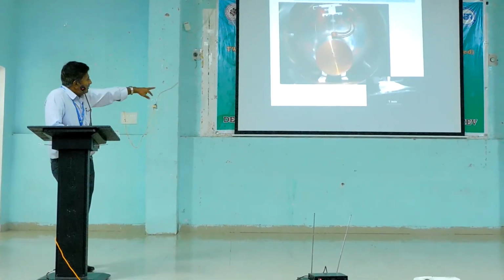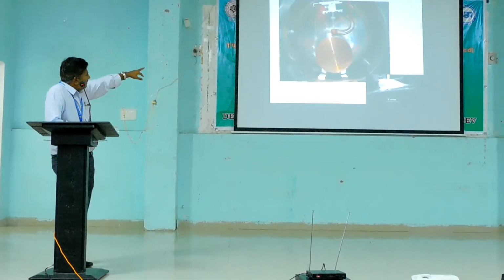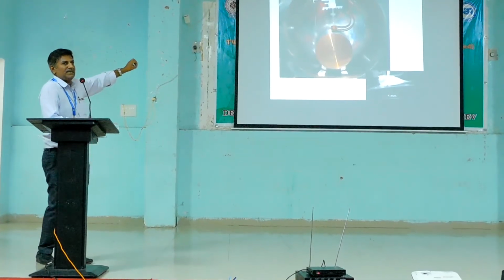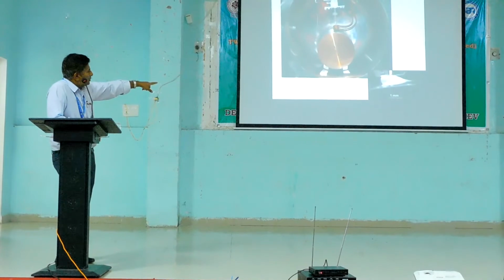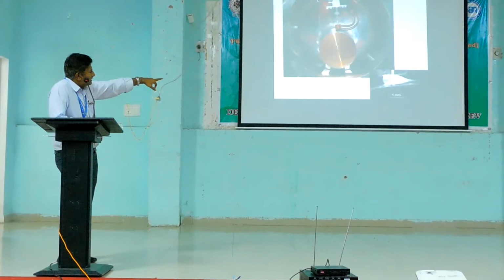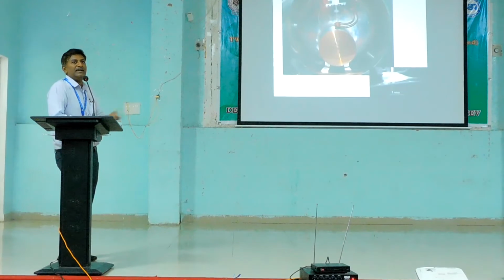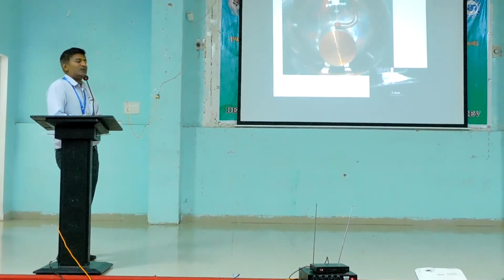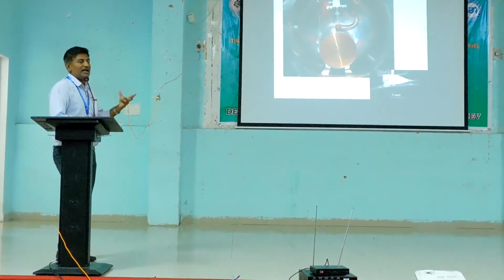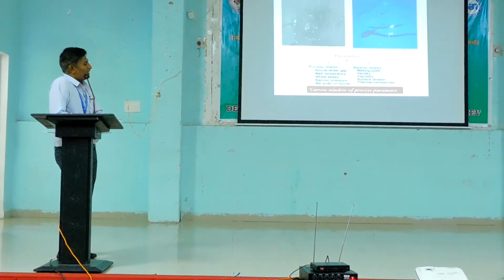Next. You can see the image below is a magnified image of the region where there is a quartz nozzle. In the quartz nozzle we are melting the alloy and ejecting it onto this rotating copper wheel. I have taken a magnified view showing the liquid metal coming and getting solidified on the copper wheel. You need a very high speed camera. Normal cameras will not work because, as I told you, it happens in a fraction of a second. So you need a camera with very high frame rates. Next, I'll show you some things which we have published.